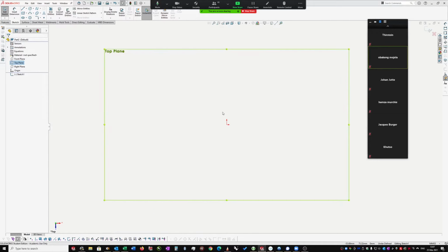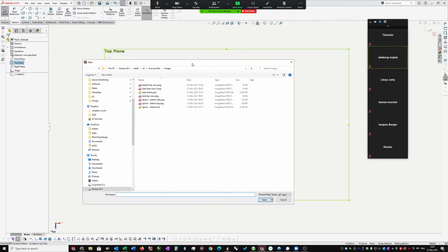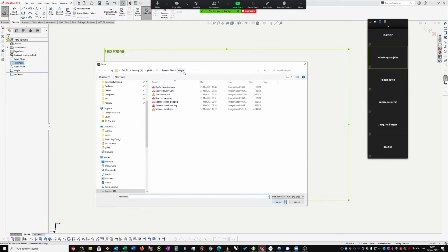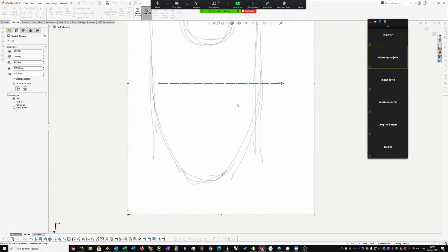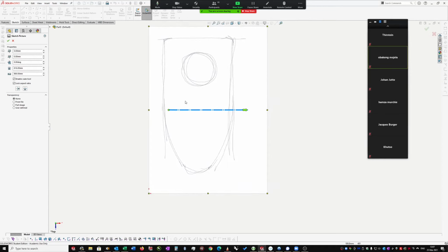If you click on that, it'll take you to the last file location that you opened. In this case it's the images where I've just dropped that PNG file. I've saved it, so I'm going to click on that and it'll drop the sketch in at the location point. So I'm going to zoom out quite a bit because it's quite large. And then this blue line here is just a way of scaling the sketch. At the moment I know that this should be about 30 millimeters across.